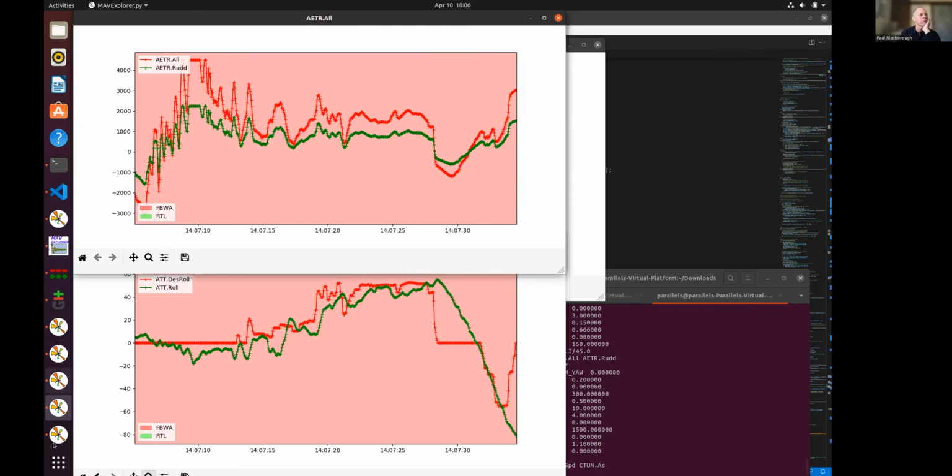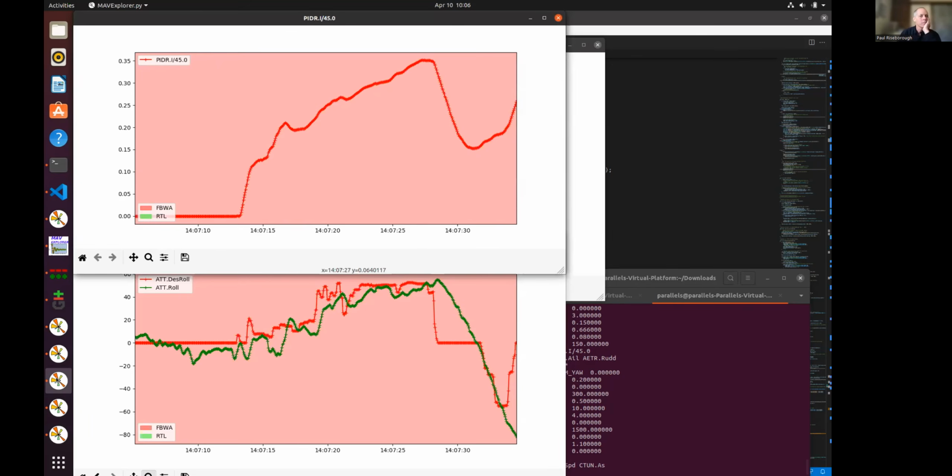That can be very effective. I've done that in cruise mode just with a rudder mix in, where the plane is flying along and I literally yawed the plane. You can see the nose yaw off, the roll loop keeps the wings level, and you can see how the throttle has to ramp up to maintain the airspeed.